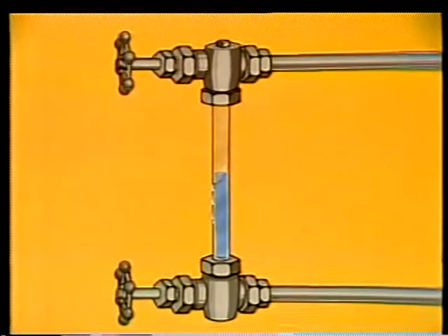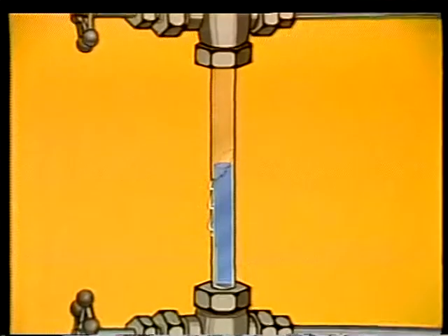Cracks in the glass are another problem that can affect gauge glasses. Cracks make the gauge leak. Cracked tubular glass gauges will leak at low pressure. At higher pressure, cracked tubular glass is likely to blow out completely. The glass in flat gauges and multiple port gauges won't crack like ordinary glass. Instead, it generally shatters. The cover plate will usually hold the shattered pieces together and prevent them from blowing out of the gauge.